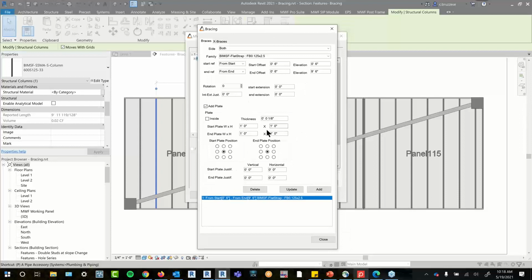So all in all, if you're using the standard 1-foot plates, you're just adjusting the offsets to meet half the width and half the height of that plate. And then the elevation you could adjust freely depending on what you need, but I've got 10-foot high walls, so I'm also just keeping that in mind and adjusting that with half the height of the plate. So that's a general rule, I'll just say, is to use whatever half the width and half the height is and use that as your offset.